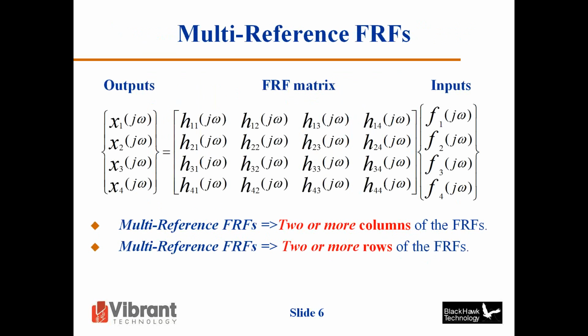Now, here is a more specific case, what we call a FRF model or matrix model. We also refer to it as a MIMO model, multiple input, multiple output model. Now you can see that the transfer functions have been replaced with functions of frequency only. And there's a j in there, square root of -1, so it's an imaginary frequency variable, as opposed to the complex Laplace variable or complex frequency variable, we now have just an imaginary frequency variable.